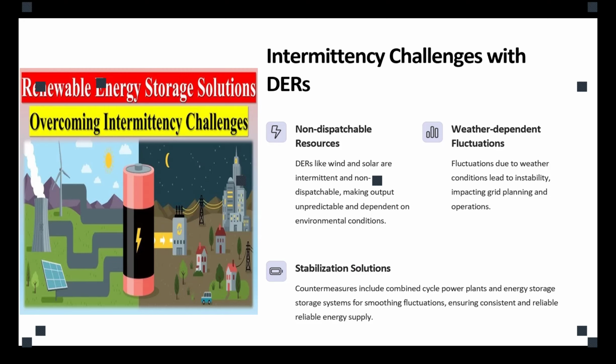Another part is that most of the DERs, as we said, are inverter-based resources, like wind generation or solar power. They are vastly influenced by weather conditions. So it's not like a synchronous generator, where the control system could mandate a certain amount of power out of that generator, and there is a solid capacity for a generator.